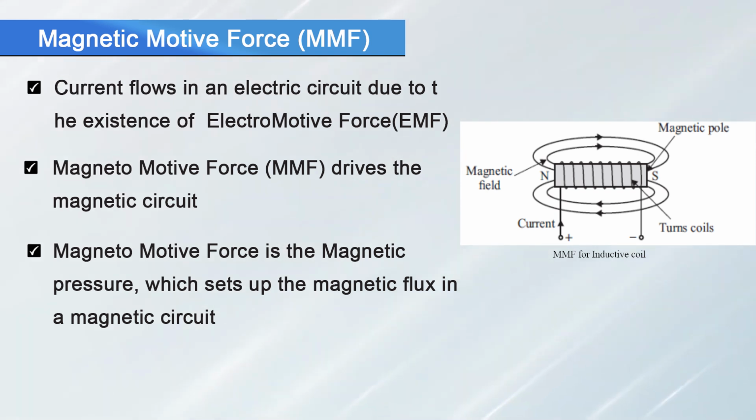Although the permeability is constant in free space, this is not true for iron and other ferromagnetic materials which are used in the construction of the electric machines. To understand how magnetic permeability behaves in a ferromagnetic material, we can gradually increase the direct current applied to the core, as you can see in the figure, starting from 0.